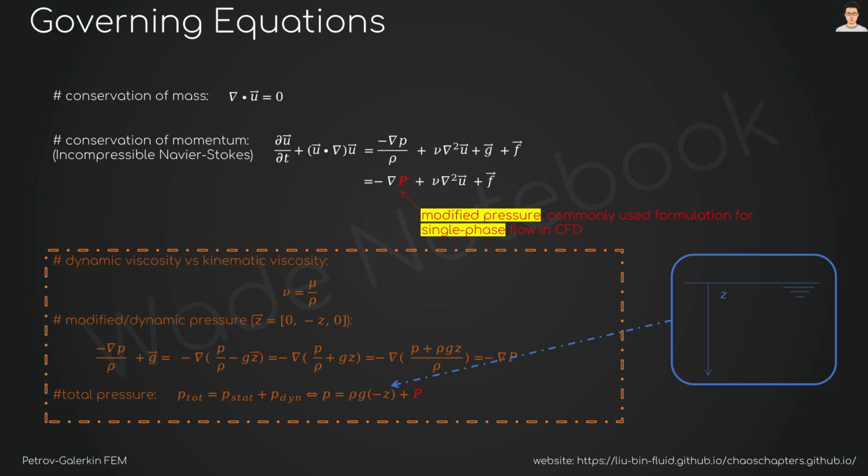Usually, the tricky parts in variational form are related to the force terms on the right-hand side of the Navier-Stokes equation. For example, if you read a number of academic journal articles, you may realize that sometimes the gravitational term and/or the external force term disappears in the Navier-Stokes equation. This is due to the careful considerations in each distinct case of fluid flow.